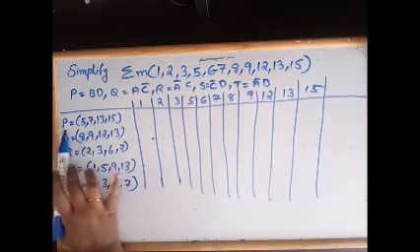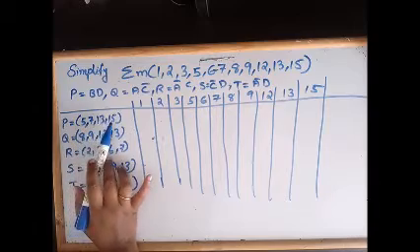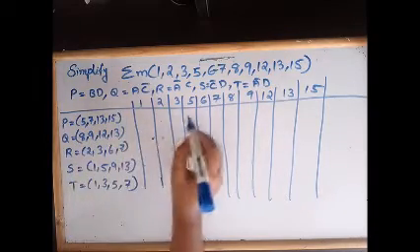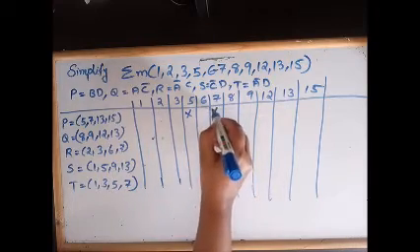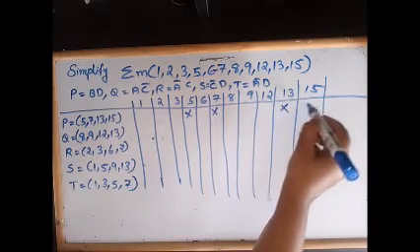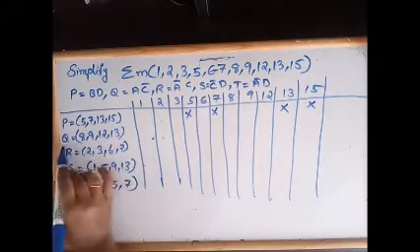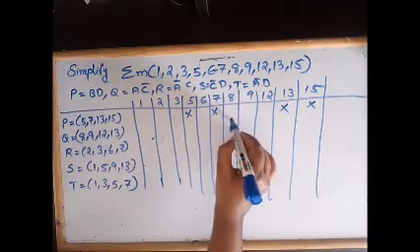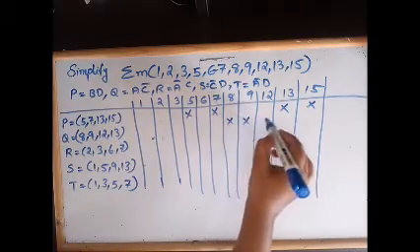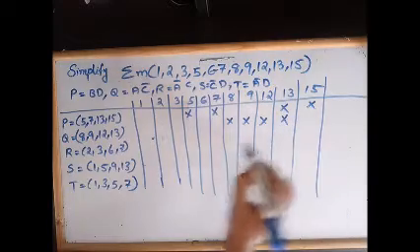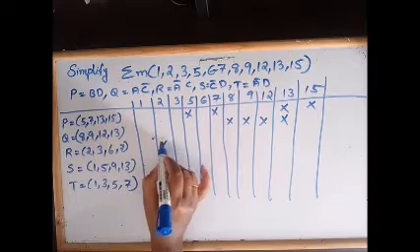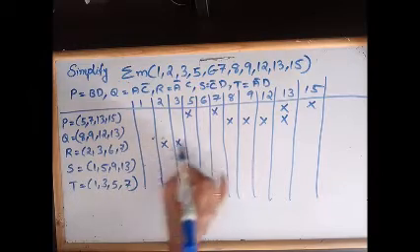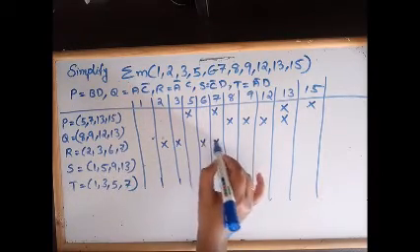So the P prime implicant consists of the 5, 7, 13 and 15 min terms. So just put a cross mark: 5, 7, 13 and 15. Then Q consists of 8, 9, 12 and 13. Then R is 2, 3, 6 and 7.